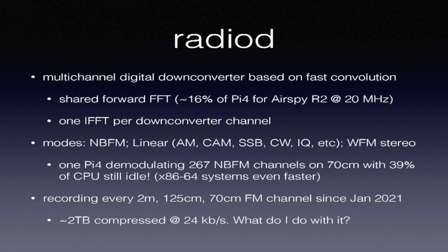So you can think of this as, take a waterfall display on a radio, and then imagine peeling off a little piece or little pieces of that waterfall display, and then converting that back into a time domain signal you can listen to. That's not quite that simple, but it almost is that simple. So there's one big Fourier transform that takes the input data from the front end, very wideband, produces all of the waterfall channels, and then you have lots of little ones that take whatever piece you want and convert it back into audio, demodulate it, FM, AM, whatever you want, and send it out.